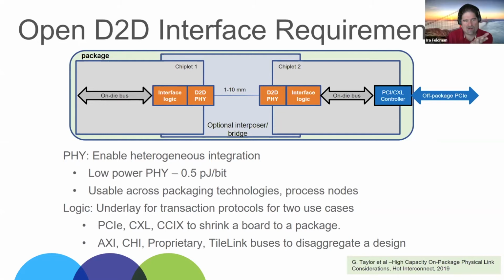So a question that happens in system design when you have multiple chips: if you have a lot of I/O pins and you can't randomly reassign them, and you have two different parts and you have to do the interconnect between them, you get into how many layers of printed circuit board routing you need to do the crossover, for example. And I'm assuming people don't want too many layers of metal on their interposer or their bridge. So how do you solve that?